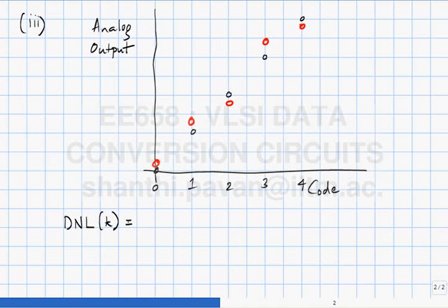In practice, it will not be exactly that, there will be deviations depending on random device mismatch, things like that. You know that the nominal must be so much, so all the real information is in the deviation around the nominal, right. So it makes sense to only quantify that, and it's understood that the deviation should be around the ideal LSB.